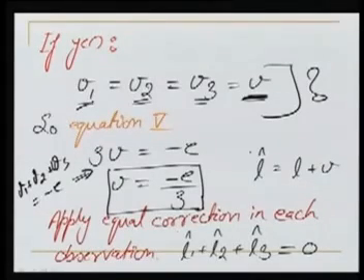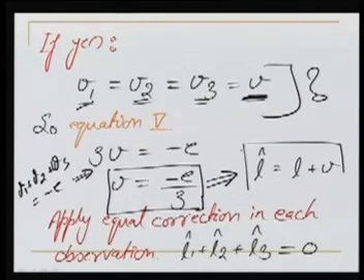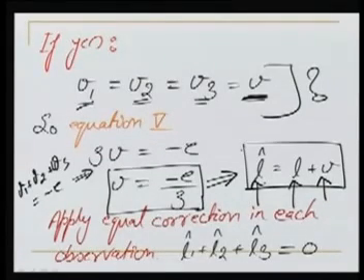Now with this, if we know the value of residual, I can apply it on the observation L. This V is being applied to get the estimate. So the estimates will now satisfy my functional model. So what have we seen in this example? We saw a method of adjustment. We had these three, L1, L2 and L3. We made an assumption that L1, L2 and L3 have been observed with the same precision. So the error is the same.